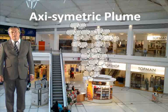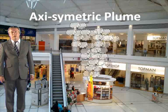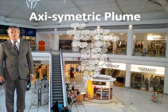Finally, we'll look at the axisymmetric plume models. Don't forget this is the most common one to apply, especially if it's not known where the fire load will be located, as this model will result in the largest mass flow rate of smoke and therefore the highest system requirements. When looking at the axisymmetric plume, you have to determine whether it's near or far field.